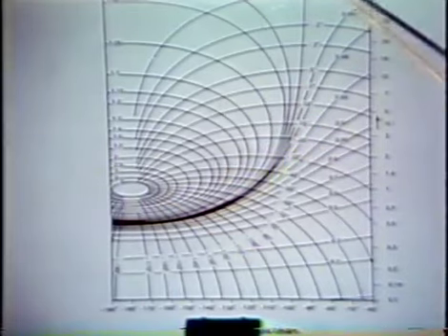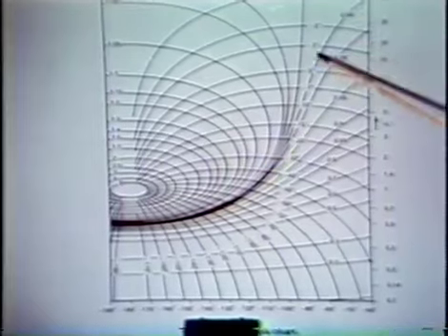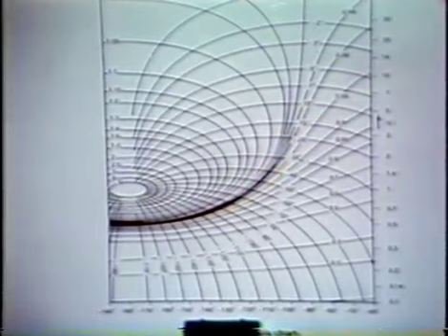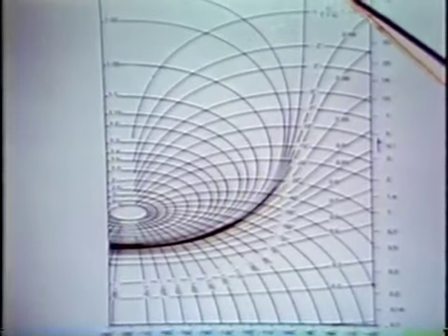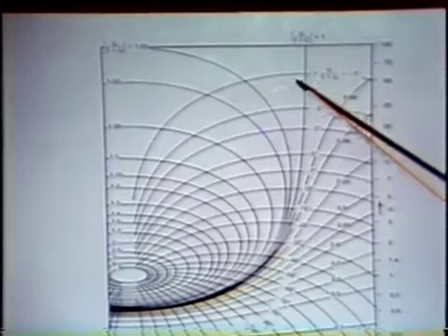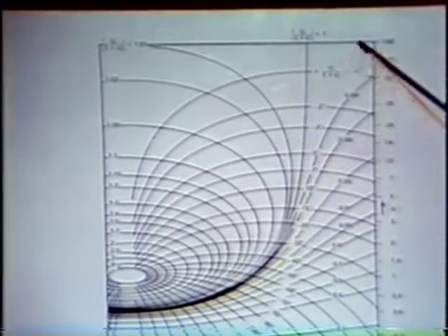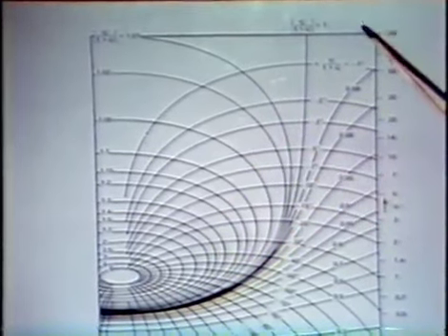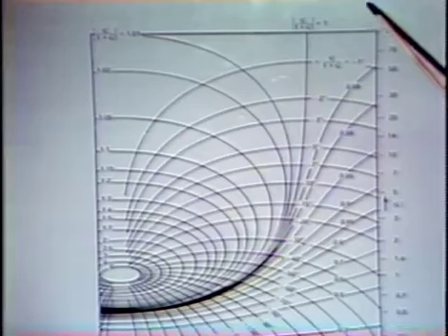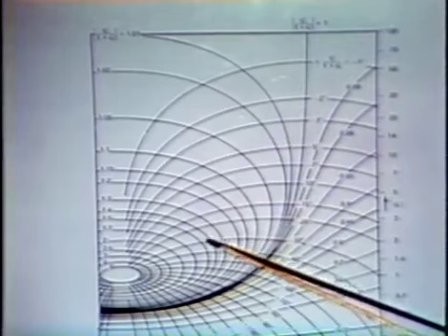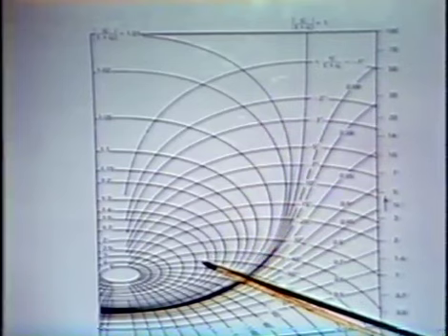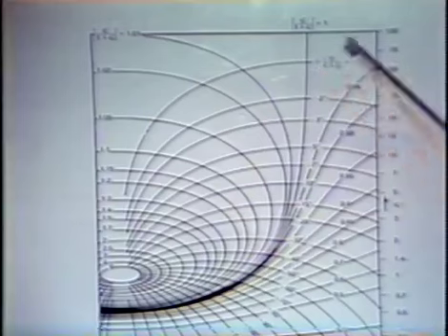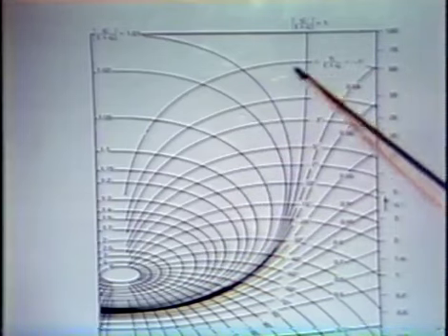We can imagine plotting a gain phase plot for a loop transmission. We can plot an AF plot, really just the left-hand portion of the Nyquist construction. We could plot that in this plane. Omega would be a parameter running along that curve. And what we do is find we'd be able to get the closed loop transfer function by simply evaluating the magnitude, and if we cared to, the angle of G over 1 plus G as we progressed along the contour in the gain phase plane.